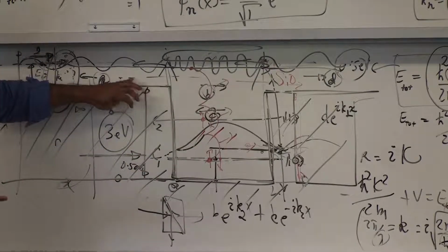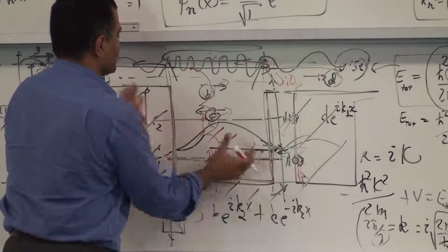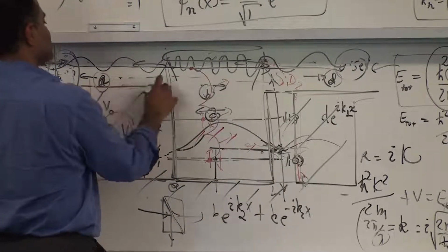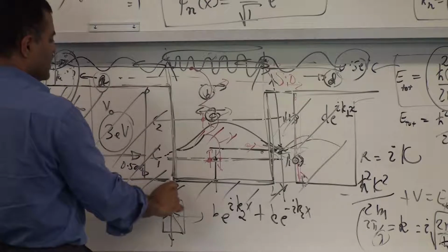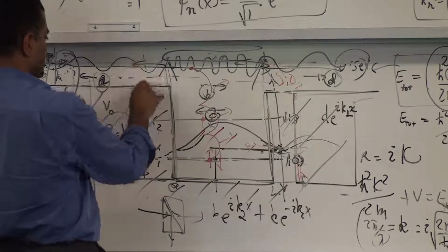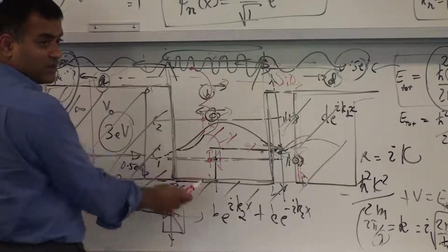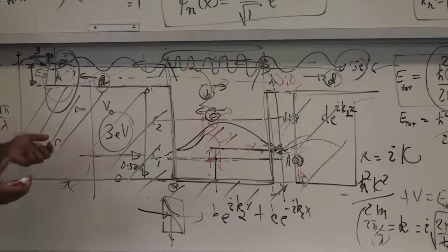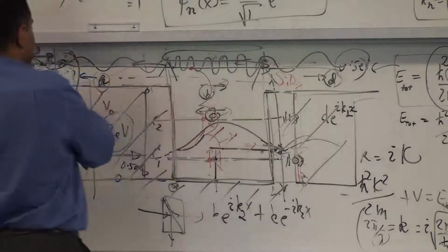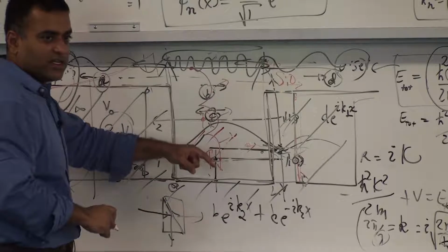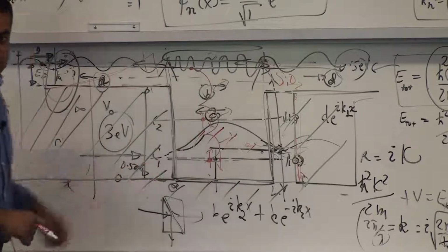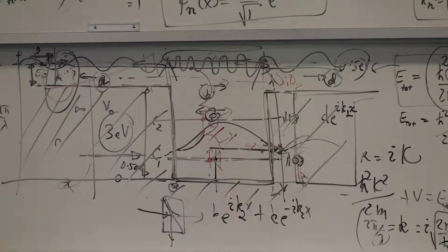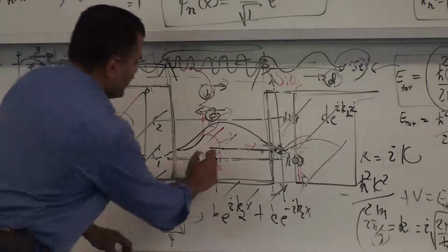Charge gets trapped, and when you get trapped, what happens is this potential barrier. This is a slight more complication. The potential barrier height doesn't look like this. It starts looking more like this because the electron is repelling the other electrons now. So it starts floating up and down now. And that leads to things like Coulomb blockade and all that sort of thing. That's called Coulomb blockade. You can see what it is. It's just Coulomb repulsion that's making it harder for electrons to get into the well again. So that's the Coulomb blockade effect. Right? This happens very often in what's called single electron transistors. So this is something that people deal with.